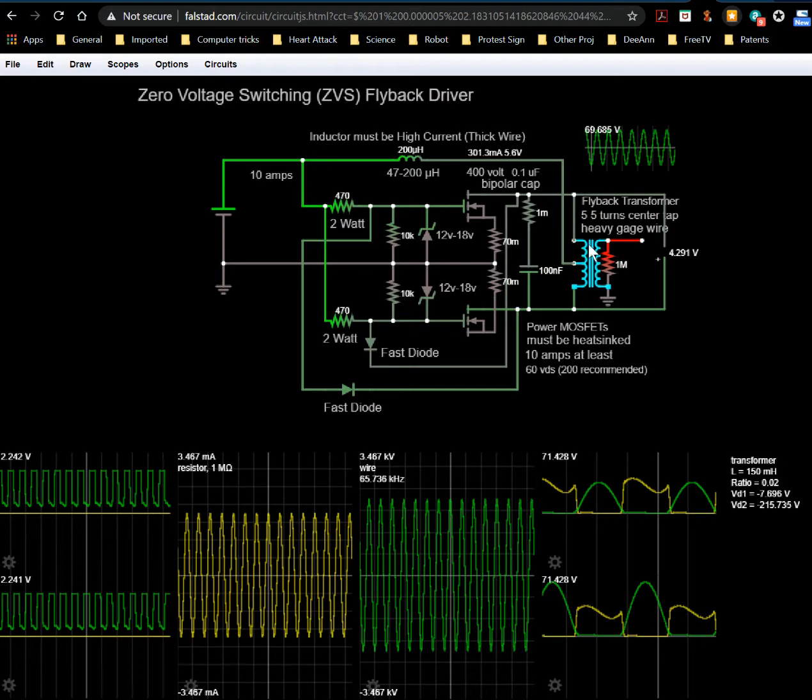So at first there's no current that flowing through the inductor. It's got zero current flowing through it, but the voltage across it is really high. It's 24 volts. Partly the reason it's looked at as resisting the current is because it forms 24 volts inside the inductor, which is an opposition to the 24 volts that we're applying across it, right?